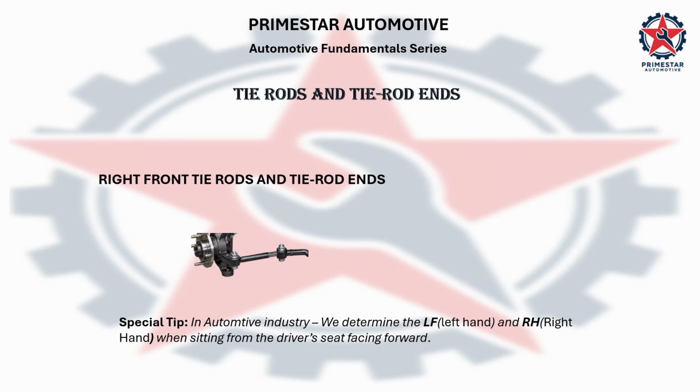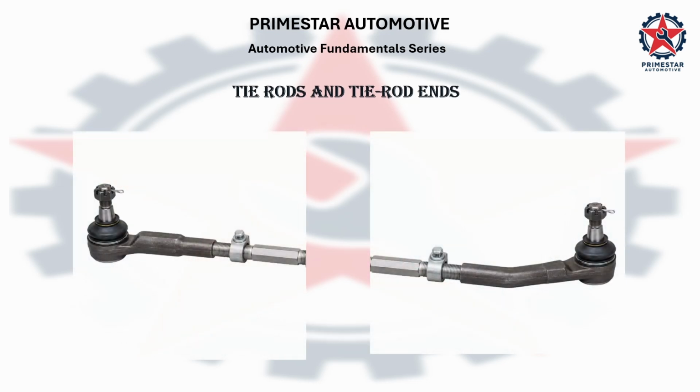Look closely at each end of the linkage. The inner and outer tie rods carry steering movement toward the steering knuckles. Here are the tie rods in focus. They form the final physical connection between the steering gear or the steering rack and the steering knuckles. When the tie rods move, they push or pull the knuckles.